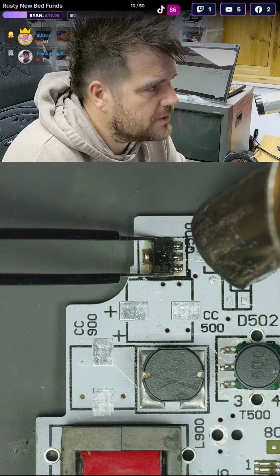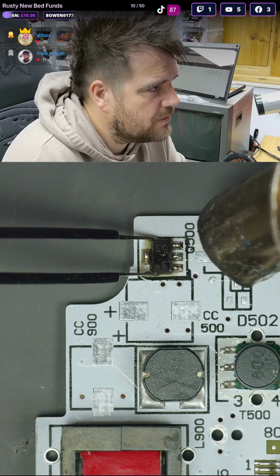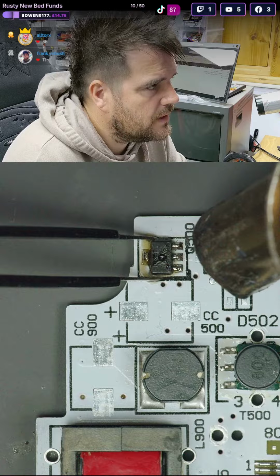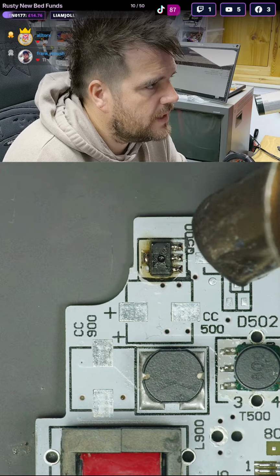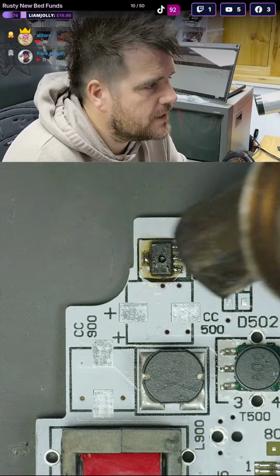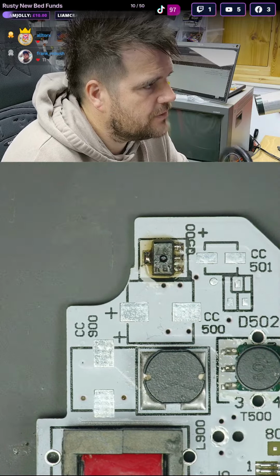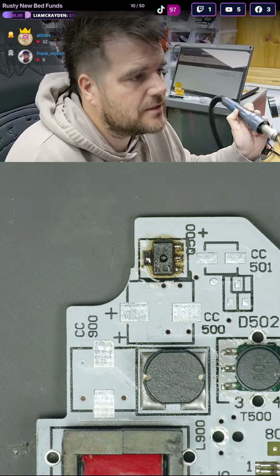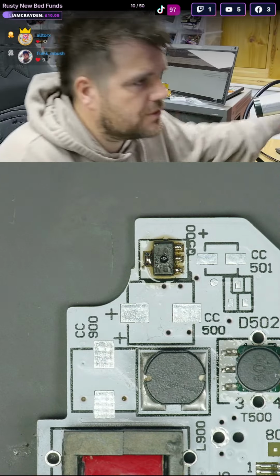I'm just holding it in place with the tweezers until I see some of the solder flow, like there, and now I can let go, and there's the dance that shows it's all soldered in nicely. That dance is showing that surface tension is pulling the chip back into centre of the pads, so you know the solder's good.